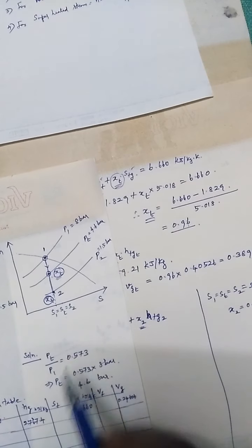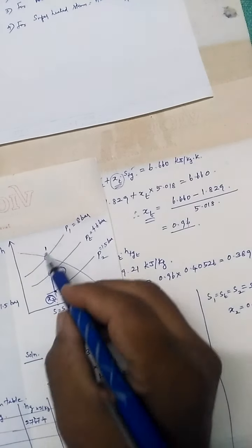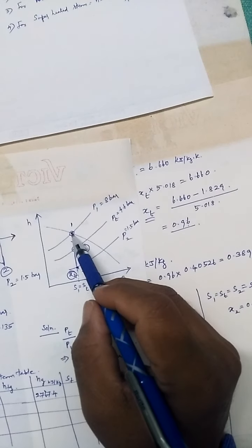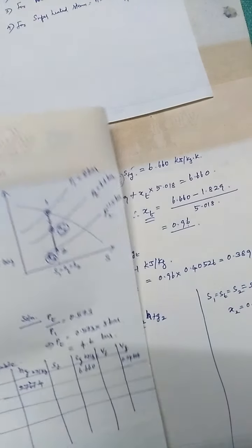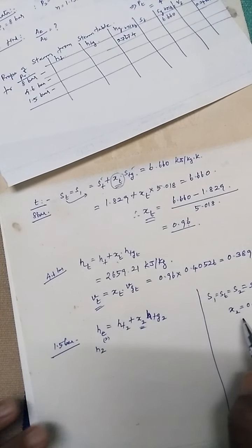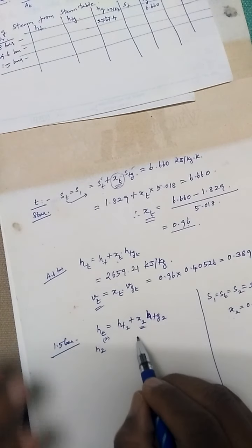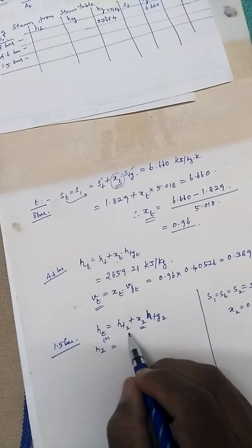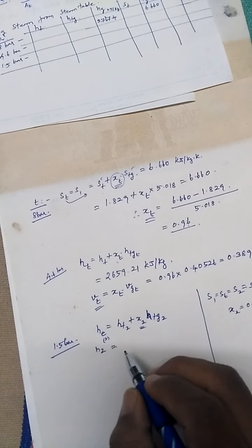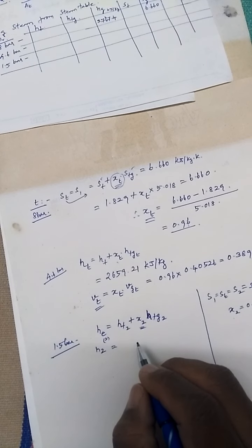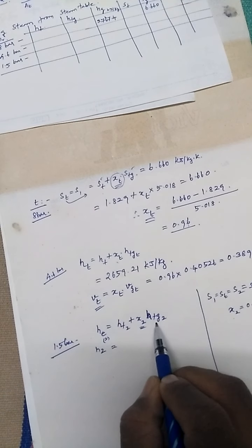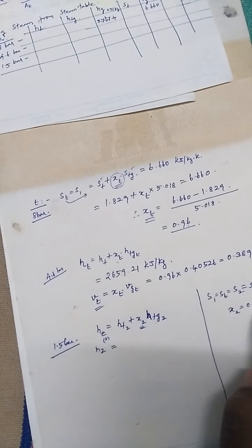So the dryness fraction is becoming lower and lower. Here it is 1, that is the saturated condition. So using this x2, putting the values here, hf2, that is the fluid point for 1.5 bar, and hfg also at 1.5 bar, x2 0.9.